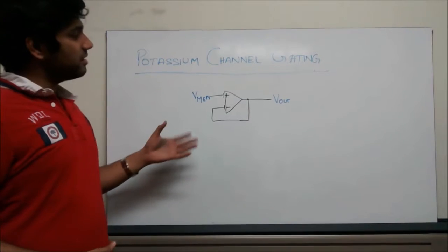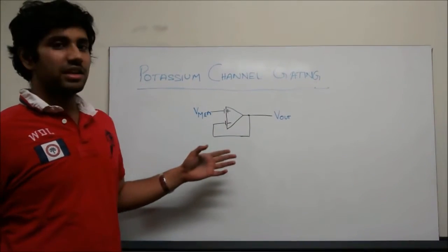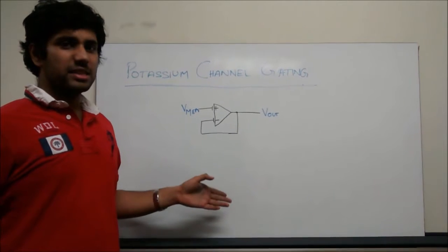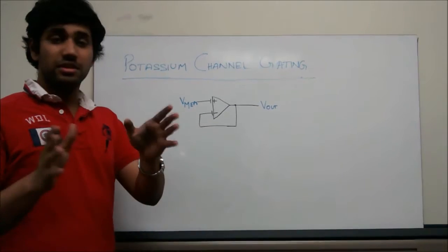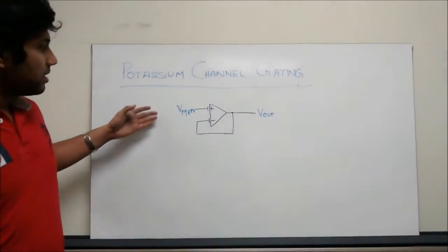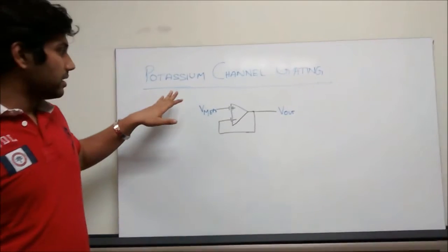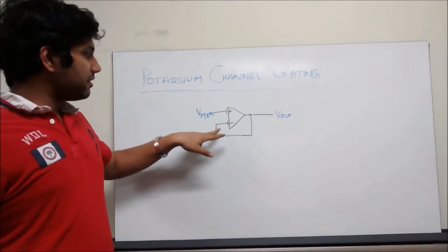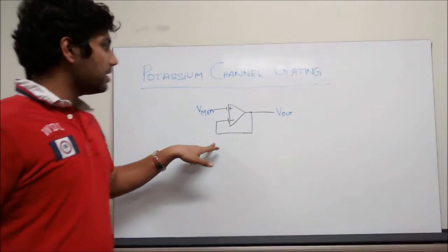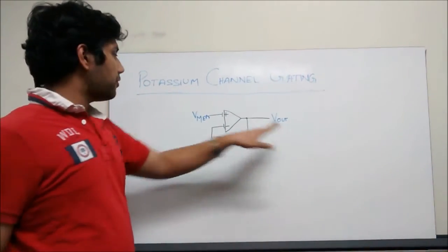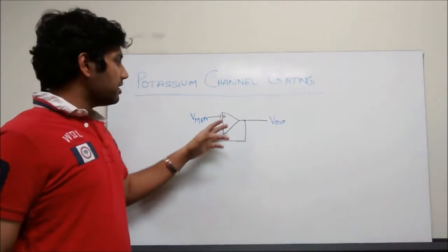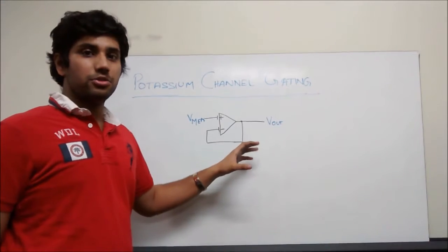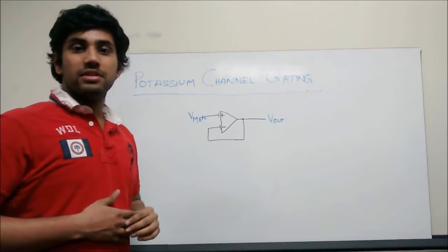Gating circuit. This circuit is effectively an FGOTA connected in a voltage follower configuration, and this behaves as a low pass filter. As such, the output values follow the input. Here the V membrane is the input, and the negative terminal is connected to the output as feedback. So effectively the output voltage follows the input voltage, and by varying the I bias values of the FGOTA, we can affect the output values to some extent. The output of this circuit will be explained by my friend Kuppa.